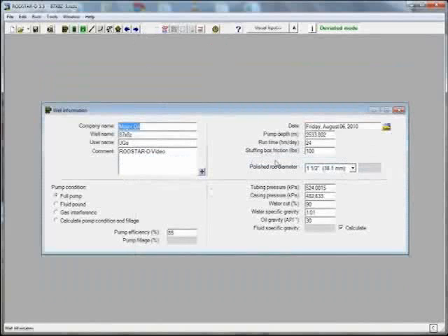Okay, now another thing that I wanted to discuss is you can switch back and forth between metric and English units, no matter what units you have selected in setup, by simply pressing F2. For example, if I am in the pump depth field and press F2, that switches to feet, and to indicate that we are in the opposite units compared to what we selected in setup, the field here becomes green. Now if I leave this field and click in the next field, it'll go back to its original unit, which is meters. So that is how that works.